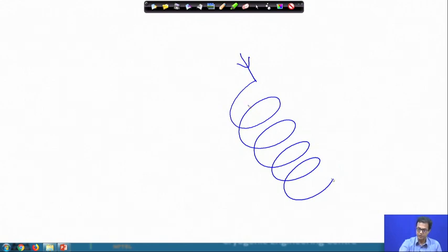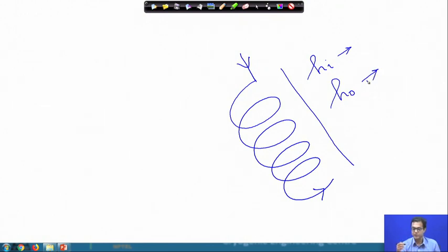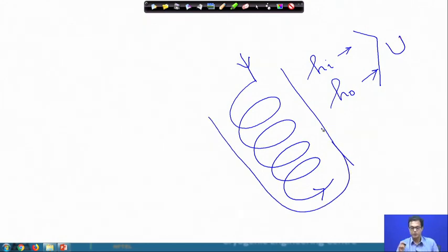It has to be a concentric tube, and you have to make a coil of it, and as soon as you make a coil of it, both the internal heat transfer coefficient and the outside heat transfer coefficient of the annular space will change, and that will of course change the overall heat transfer coefficient. So, it will become a different problem, but we are not going to solve it at this moment. We are only happy with the total length of the exchanger, and that has come to be 66 meter around.